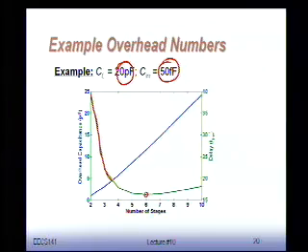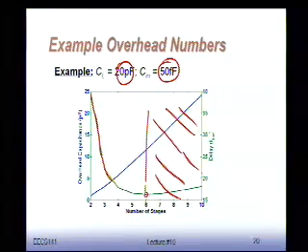Obviously, doing more stages than necessary is always a stupid idea. It doesn't help you for anything, right? I put more and more inverters in between there, your delay goes up and your capacitance goes up. So you don't want to be here. Like on the right side here, that's really bad design. I won't give you a very good grade if your project ends up somewhere up here. You want to be on this side. But that's where the trade-off game is, right? You see delay goes down, capacitance goes up, and I can trade off the two with respect to each other. Okay?